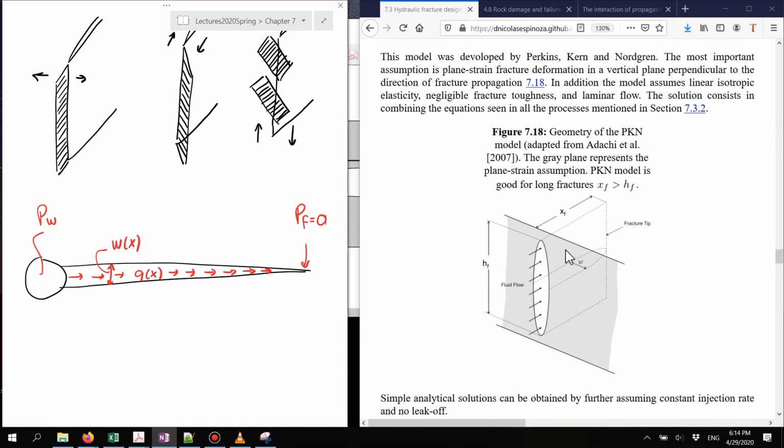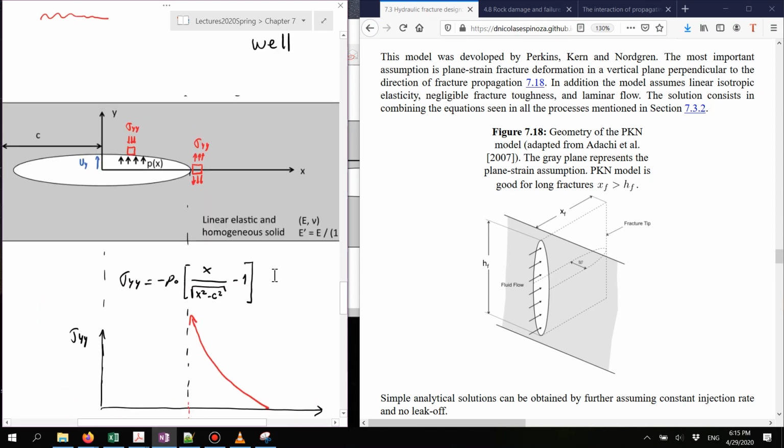is going to assume that we have a constant fracture height and that the cross section of a fracture is given by an ellipse with a shape which is given by a constant pressure at a given distance from the wellbore. So this problem that you see over here, now in these semi 3D dimensions, we solve what is the width at every point along the fracture, and you see that it varies with depth with this equation.